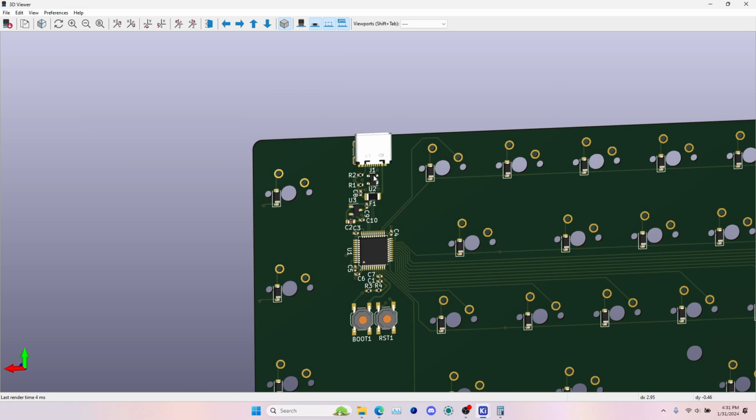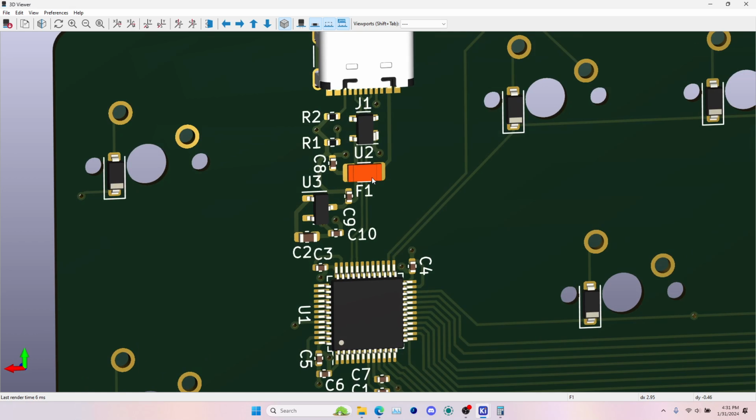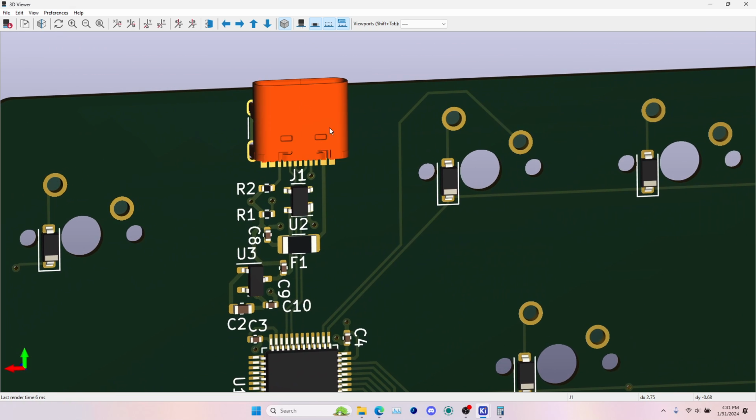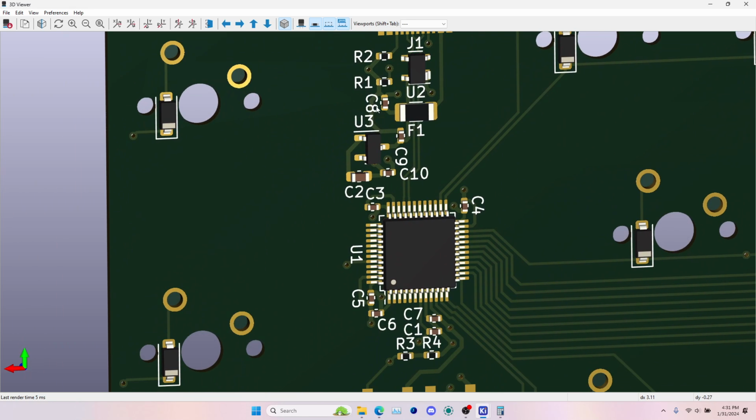And you can take the USB port and the ESD. So J1, U2, R1, R2, and the USB port. And then C8. These components, these 5 components, and the USB port, that's our USB circuit, right? That's our ESD protection, our power, our fuses, our filtering, our main filtering cap, or like our first filtering cap.